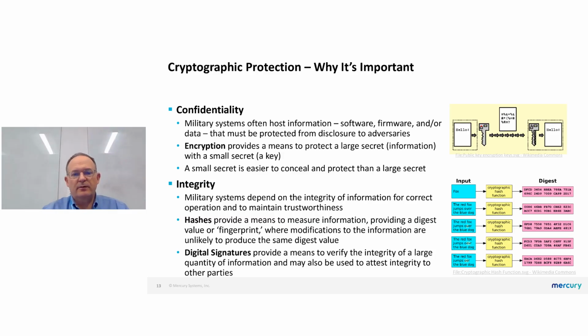For example, consider a hard drive full of terabytes of information that might have been collected from a sensor, and it might be something you want to maintain as a secret. It's very difficult for all that data to be stored in a way that protects its confidentiality without the use of cryptography. So with cryptography, a relatively small function that can be heavily protected can protect the key and protect the operation of the encryption function, so that data is better protected.